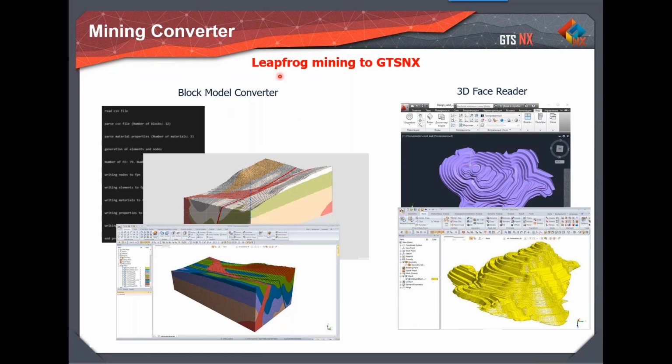Then we have a mining converter. The name itself is mining, but this process can be used in other kinds of projects as well. Suppose you're dealing with Leapfrog and you have some models in Leapfrog. All you can do is simply export that Leapfrog data into a CSV file, and that CSV file can be imported into GTS NX. All you need to do is just import it, and the software will automatically consider the blocks that are present in Leapfrog as mesh in GTS NX. So basically you're importing the mesh into GTS NX.